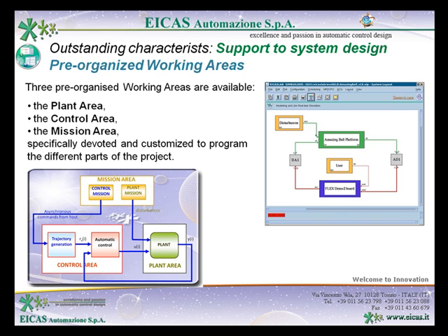For instance, in the Amazing Ball use case, we have modeled the Amazing Ball by using the continuous plant block, here named Amazing Ball Platform, which represents the plant area, and which is an analog block, while the control strategy is implemented in the block FlexDemo2 board, which represents the control area, and which is a digital block. For connecting analog and digital blocks, you have at disposal the analogic digital and digital analogic converter blocks, which are blocks available in the libraries.